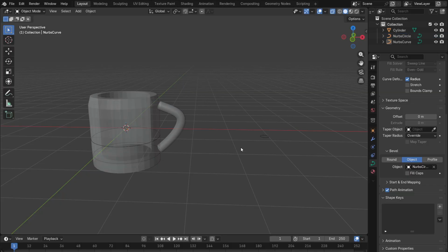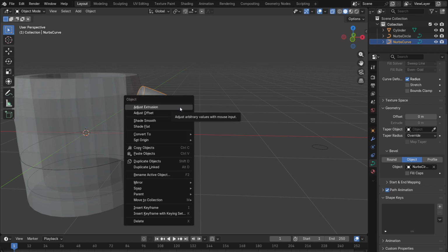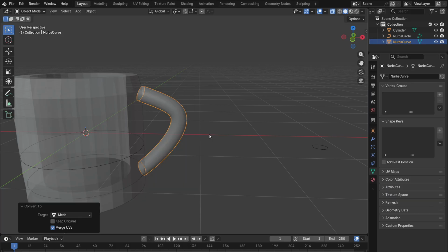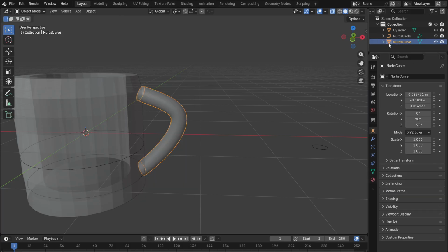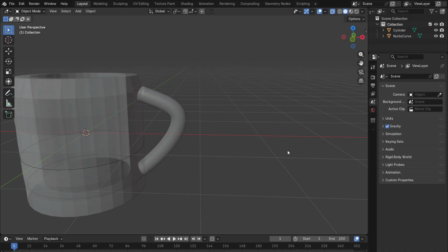Do not delete it yet. We're going to delete it. Click here on the handle, make sure it's an independent object, right click, and go to convert to mesh. It's going to convert it to a mesh. Can you see this reverse triangle? This triangle actually is not reversed. It is now a mesh, and this is still a spline, right? Can we delete it? Yes. If you delete it before the conversion, it's going to remove its effect on the handle.